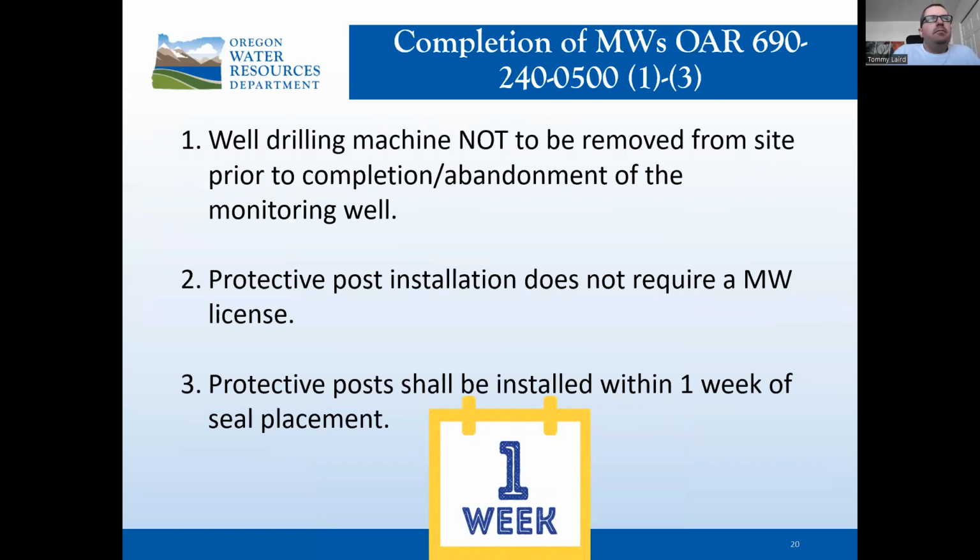For completion of monitoring wells, this is in OAR 690-240-0500. The well drilling machine shall not be removed from the site prior to completion or abandonment of the monitoring well. The protective post installation around above ground wells does not require a monitoring well license. Additionally, it can be installed within 1 week of the seal placement.